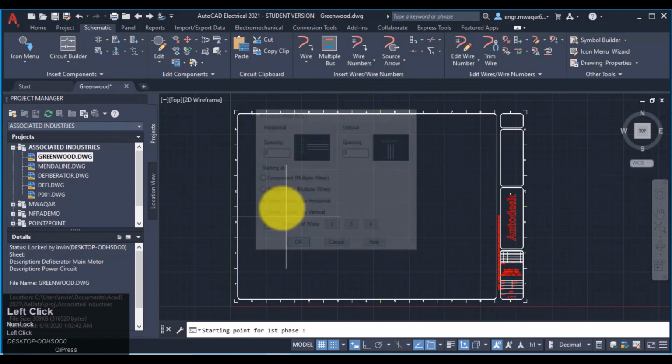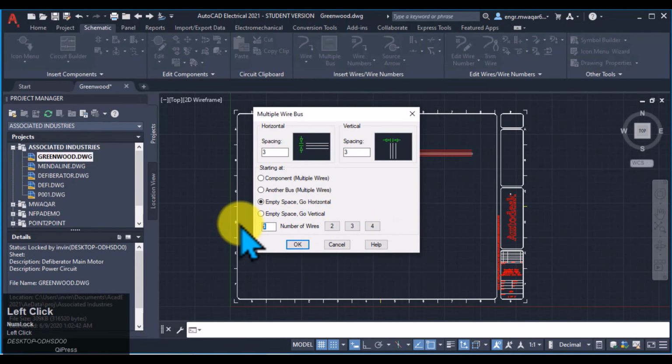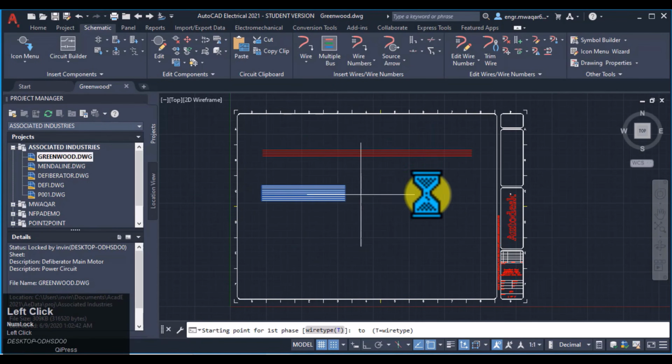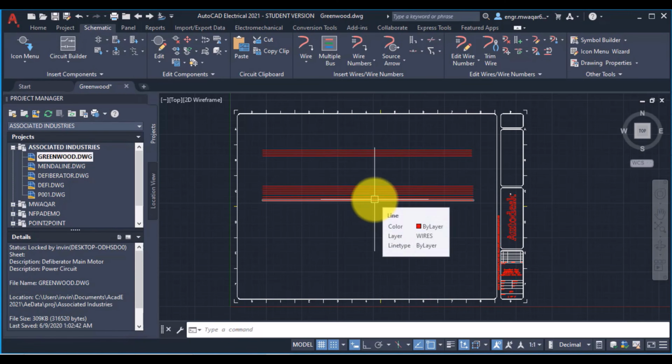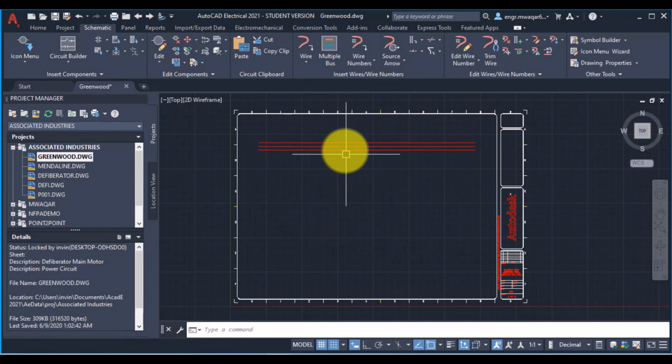Why would you want that? It sounds like it breaks the automation. It's vital for retrofits or maintenance. If a machine is already built and labeled out in the field, you can't just change the wire numbers in the drawing because the software decided to resequence. You have to lock them down to match the physical reality in the cabinet.